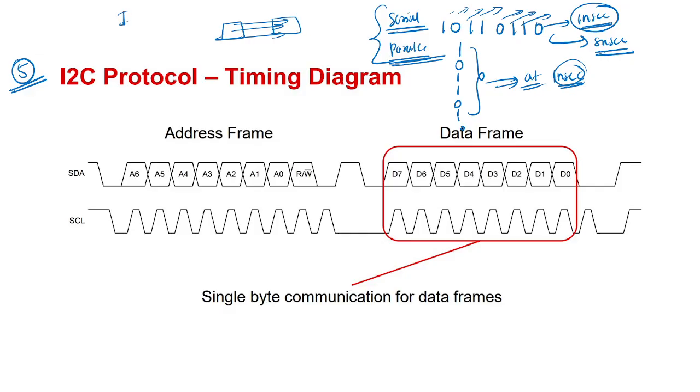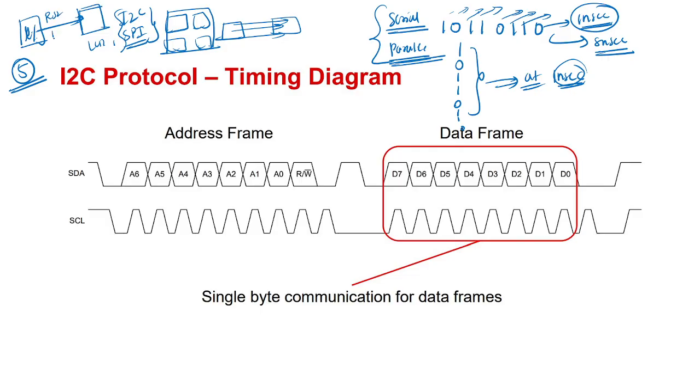So this I2C and SPI, this is onboard communication. So within the board, different peripherals are there. Those peripherals communicate serially. You need to use the I2C bus. Suppose your computer or a laptop is there. You want to interface some external peripheral like LCD or 7 segment display. For long wire communication, you can use RS-232 or UART. That is long distance communication. This is short distance communication.